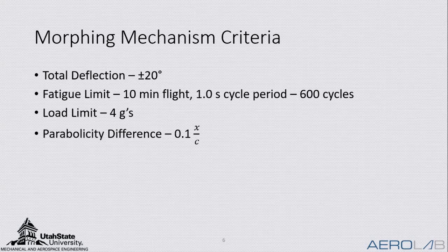They'll load up the aircraft with this weight split up in all these little sandbags, and they'll make sure that this wing is able to take this loading. For example, to ensure that they're able to take all these maneuvers, they require that it takes so many Gs, or so many weights of the aircraft, distributed along the wing. General aviation aircraft generally have a requirement of 3 to 6 Gs somewhere in there. Fighter aircraft are more than that. So we decided that a good load limit for our aircraft would be 4 Gs.